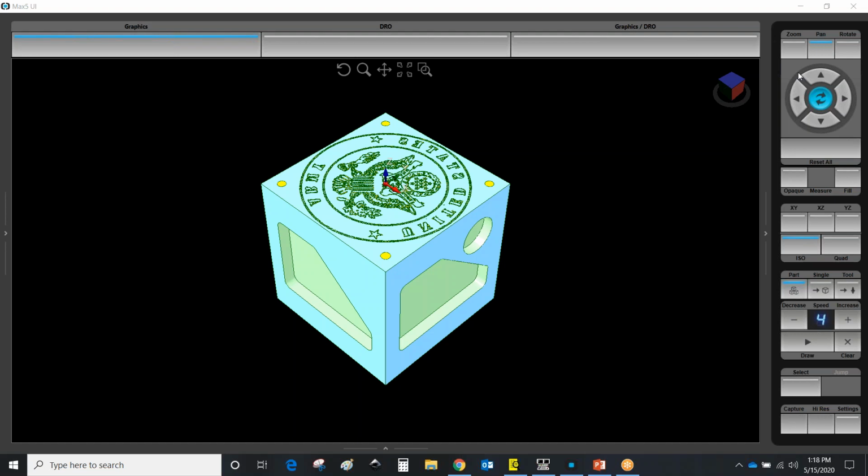Then he uses NC merge and transform plane groups to then pattern that NC merged blade 7 times around the part. So we're able to complete that impeller all with one fairly short NC program and then some conversational blocks. So that'll be something that'll be coming out here really soon that we'll be putting on social media and on YouTube. But it's definitely going to be something that'll be interesting and something that I'm not aware of anybody else being able to do.